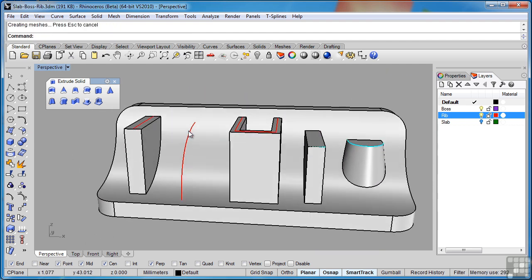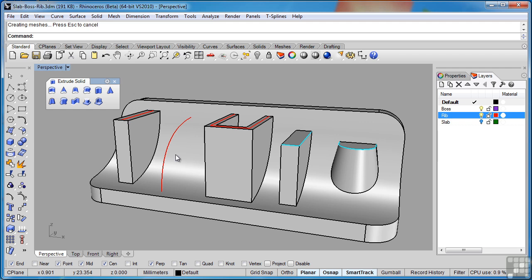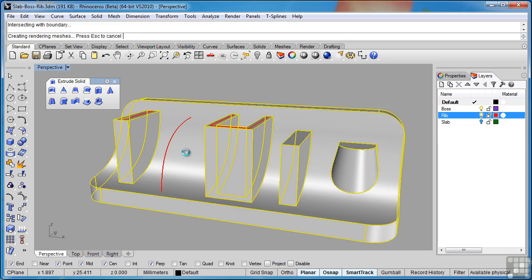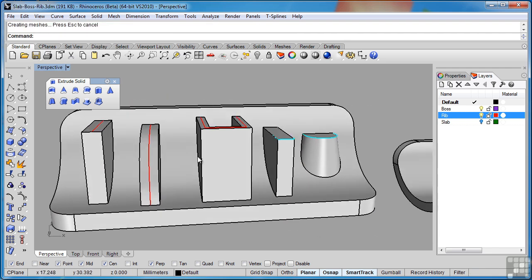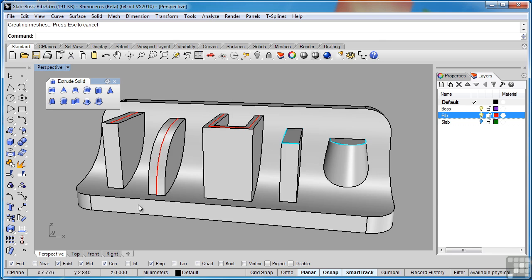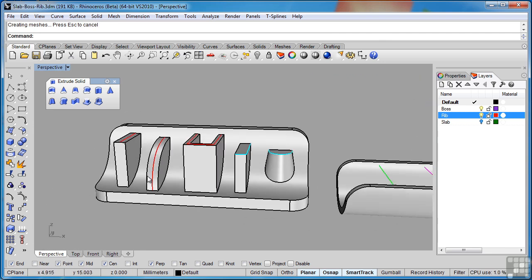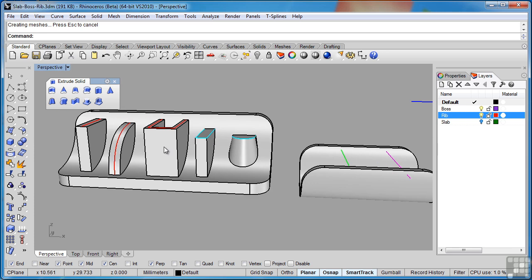You can also do curves going in this direction to make a curved rib. And that works just a little bit differently. We'll select this object. We'll select the boundary. And you can see that that didn't work. What that's doing is it's going the same direction as the curve. So if we undo this, we'll apply the command again. This time we'll change the offset from in curve plane to normal to curve plane. Basically what it does is it extrudes that shape, the distance we've given it, in both directions, and then it extrudes down, and then it booleans down right into the boundary object.